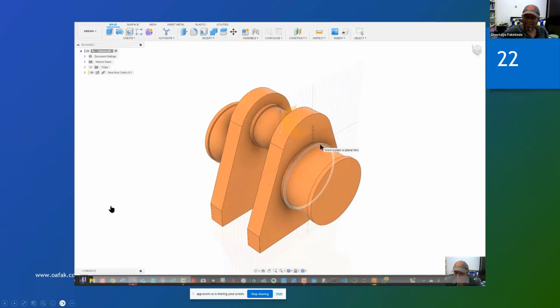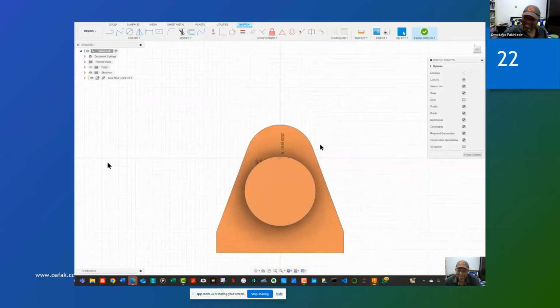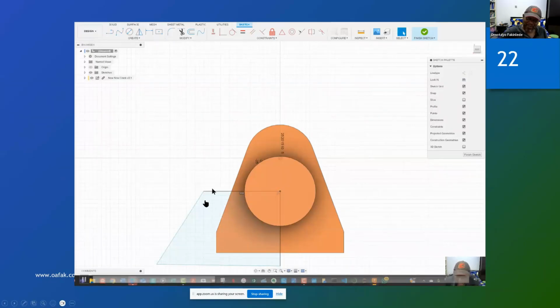We're creating our sketch on that plane. Once we create our sketch on that plane, the plane will face us, and any sketch we create now is on that plane. So we start by taking a line creation element, and we start from the center there, and we move back. After that, we move down, and then we move right, and then we close. As soon as we close, you can see we have a closed profile and it has painted it blue.